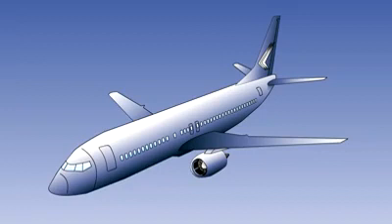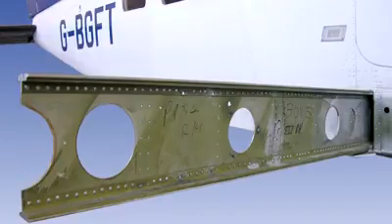Now we will look at cantilever wings, the design used by most modern airliners. The wings have to absorb the stresses due to the lift and drag in flight, and, if of this design, their weight when on the ground. This is achieved by building the wing around one or more main load-bearing members known as spars. The wing spars pass from wingtip to wingtip either as single structures or as connected sections.